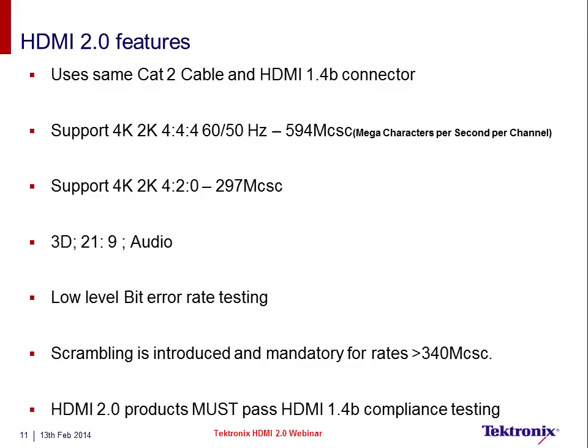And the most important thing is the fact that your 2.0 product, since it has to work with other legacy products which are already available worldwide, needs to pass the CTS 1.4b. And this ensures that the interoperability and backward compatibility amongst various categories of HDMI devices is ensured.